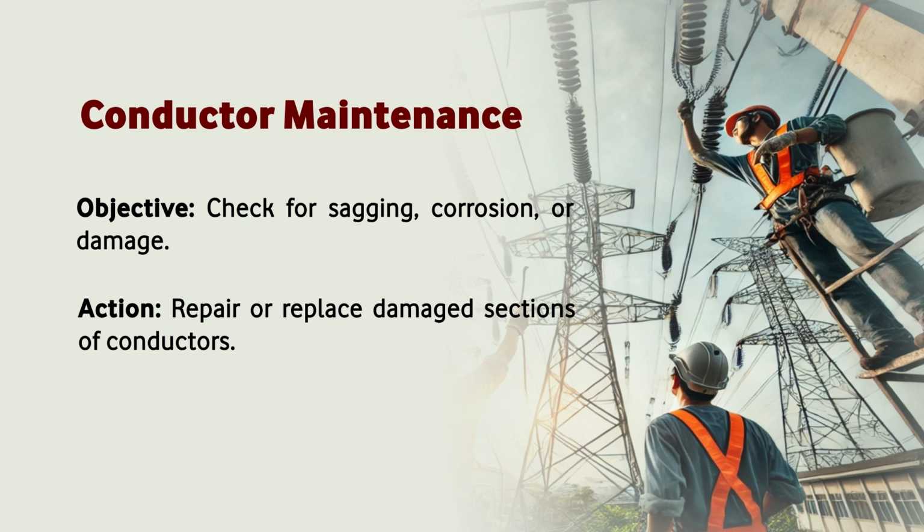First is sag and tension monitoring. Conductors are regularly checked for sag, which can occur due to thermal expansion or mechanical stress. Proper tension must be maintained to prevent sagging lines from coming into contact with trees or buildings.